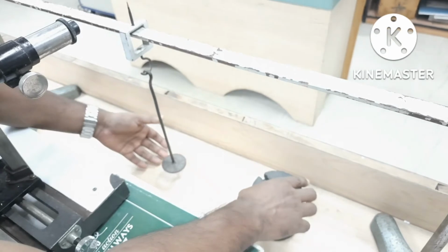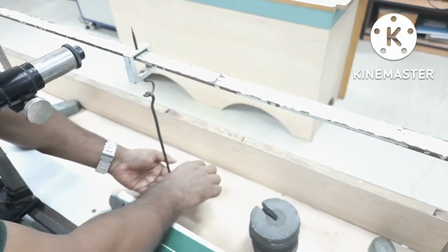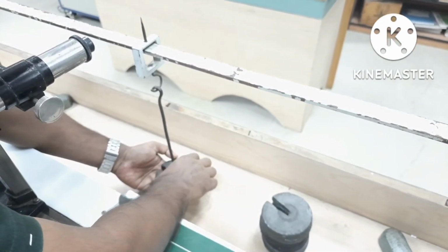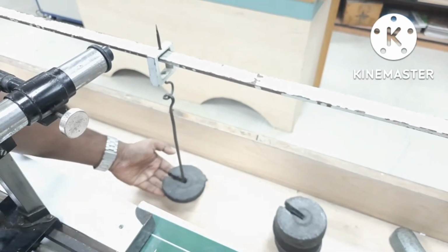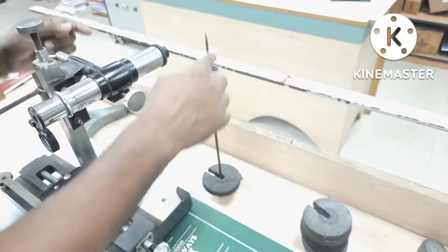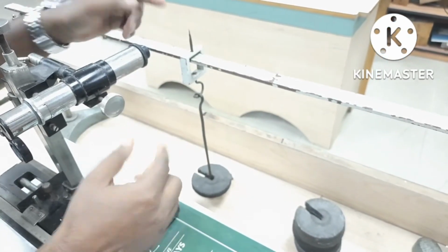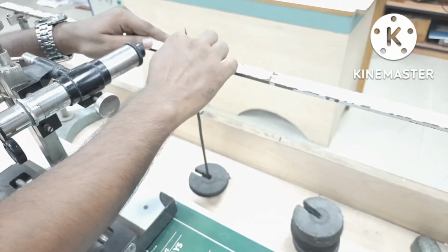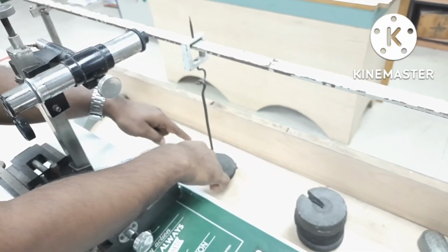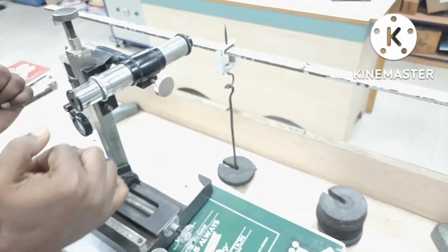Now, very carefully I am placing the load, this is 500 gram, in that hanger. What will happen? Will the tip be in the same position, or will there be a displacement of the tip? Obviously there will be a displacement of the tip, and let's see after placing the load what the picture is through this microscope. Here it is clear that now our tip is not coincident with the cross mark, but it is in the focused condition. That means there is a deflection or bending of the bar.